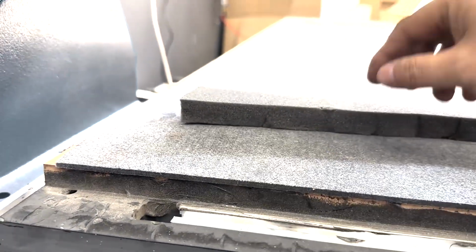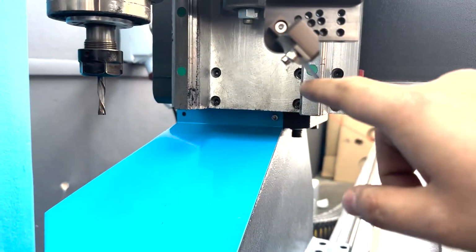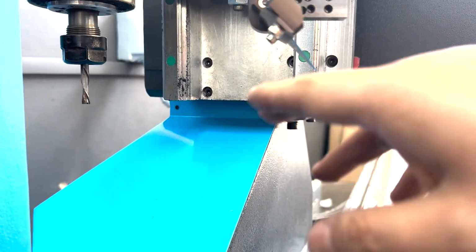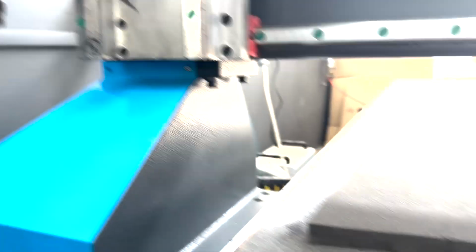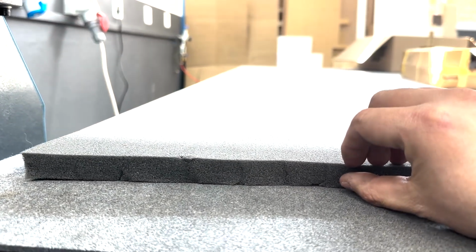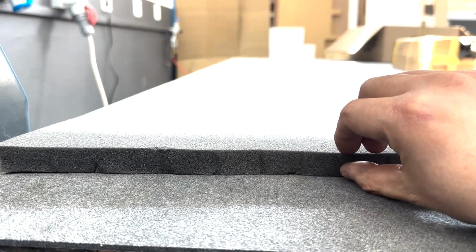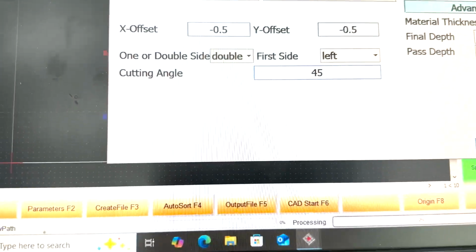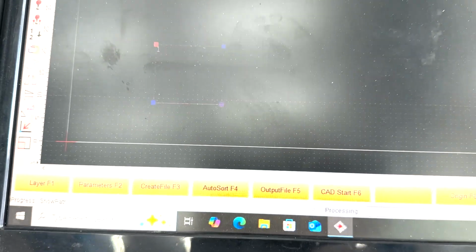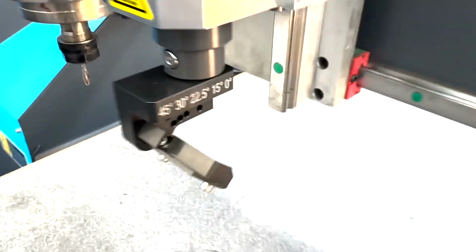You cannot just go deep like before, because you do not have a protection holder, so going deeper doesn't matter there. But with this one you cannot; if you go deep, it is deep. So you need to set exactly the thickness in millimeters. That's basically the software part. The rest is practice. Let's practice on the V-Groove cutter.